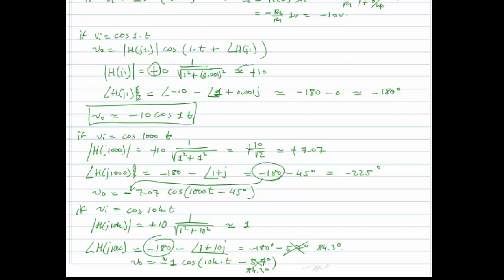So I want to filter out those higher frequency fluctuations. So I could send the output of the temperature sensor through a filter like this. That on one hand gives me some low frequency gain, maybe that's something that I need, but on the other hand it'll actually then attenuate, remove that gain, in this case of 10, and even add attenuation beyond that for higher frequencies.